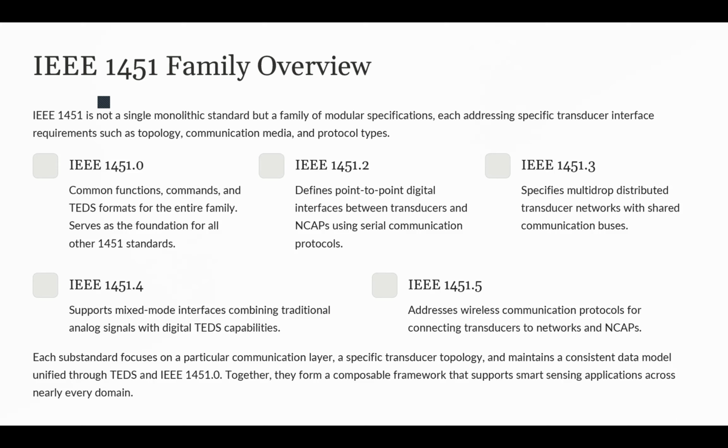Part 2, which we mentioned in the interface, covers the point-to-point digital interface, which specifies a direct digital interface between the TEDS and the NCAP using a serial protocol, which is ideal for embedded or low-latency applications. Part 3 covers the multi-drop network interface, which supports bus-oriented communication when we have multiple TEDS that share a single channel with the NCAP.